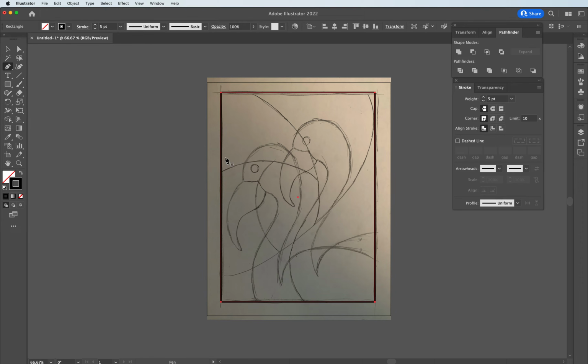I'm going to start out with going from the border over to the end of a certain line. So I'm going to start on the outside of the border itself, click a point. I'm going to move to the curve and click and drag to create out that next curve. Once I have this line ending, I can simply hit escape. It ends the line, and then I can begin drawing out another curve.